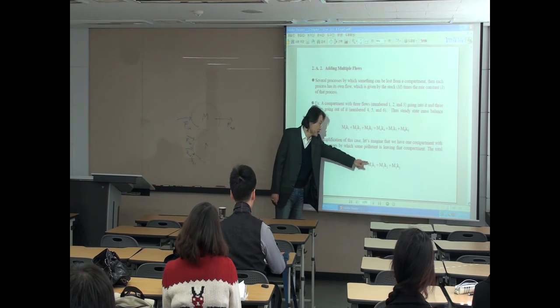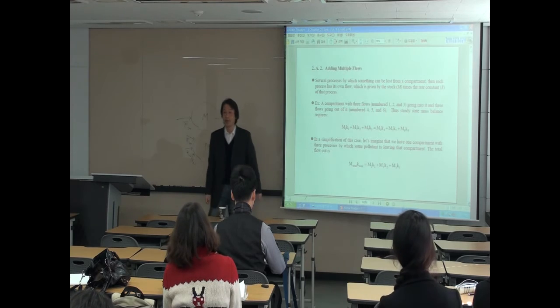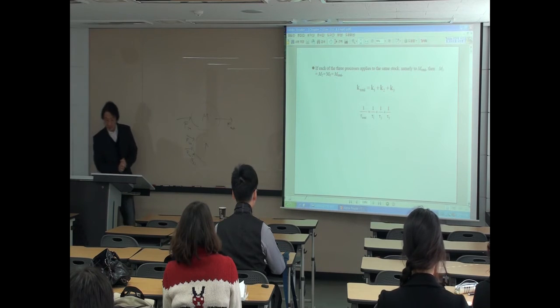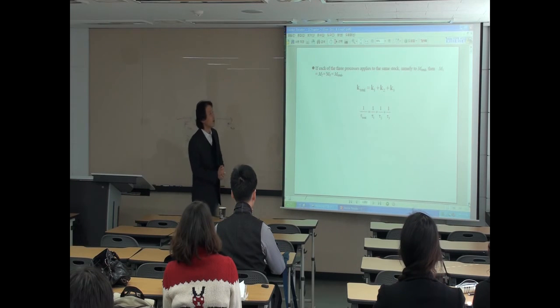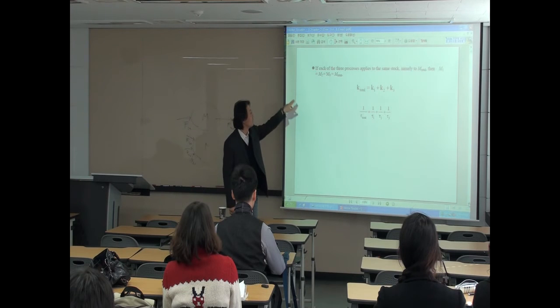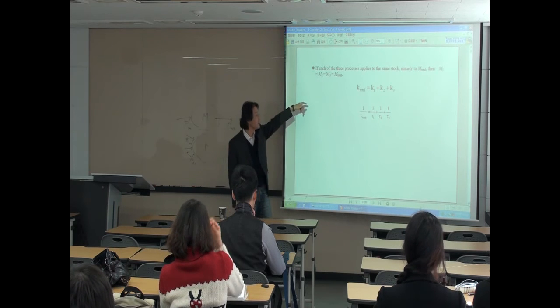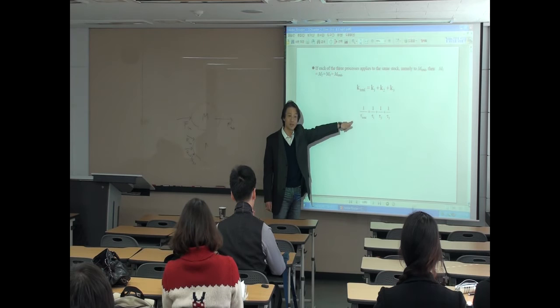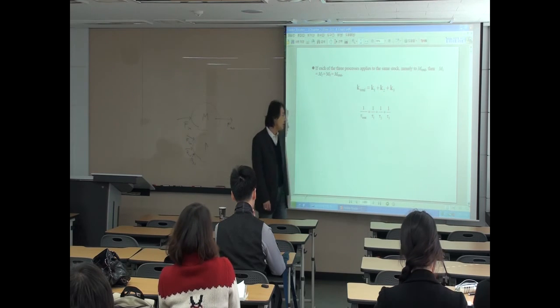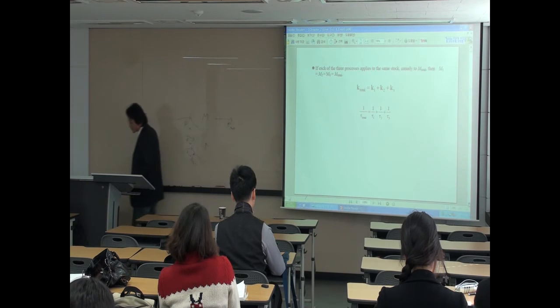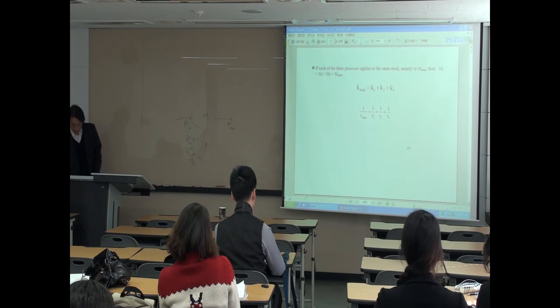So it could be M1 K1 plus M2 K2 plus M3 K3, right? Then if we assume M total equals all the stock going in, we can simplify: K total would be K1 plus K2 plus K3. This is the rate constant, and it can be converted to the residence time. So 1 over the total residence time equals the summation of the reciprocals of each residence time.